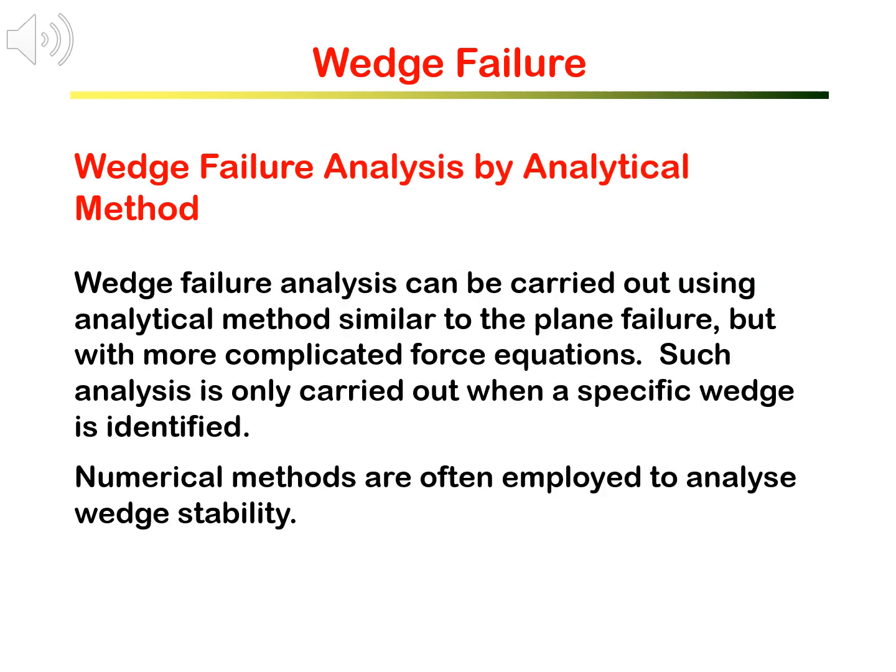Wedge failure analysis can be carried out using analytical method. The general approach is similar to that for the plane failure analysis. However, because it involves more planes, it requires more complicated force equations. Many assumptions are needed to make the analysis simple.